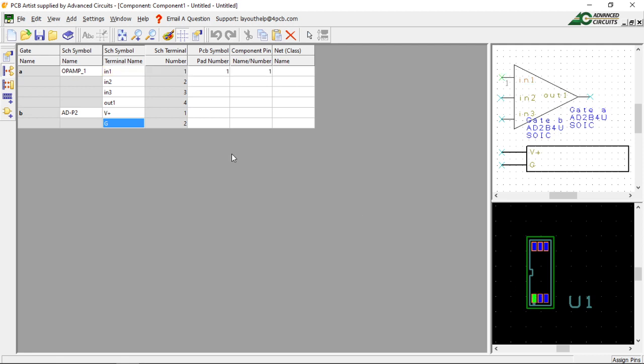Okay, you click this pin, click this, you click this pin, and you click here. Now I'm doing it in order, but for a real circuit, unless you were creating the component yourself, actually building it and manufacturing it, you're going to be told which go to where. So right now I got 1, 2, and 3 here, and so I'm doing it as if I were creating this component. I manufactured it and everything.